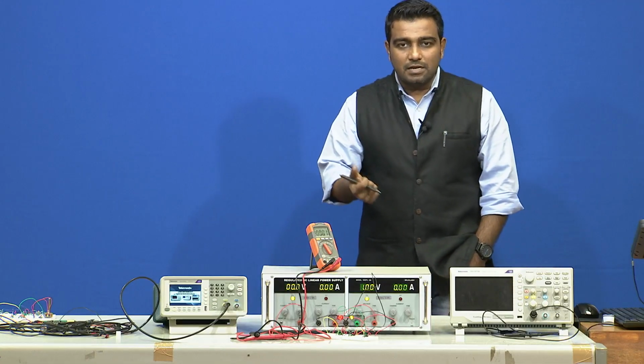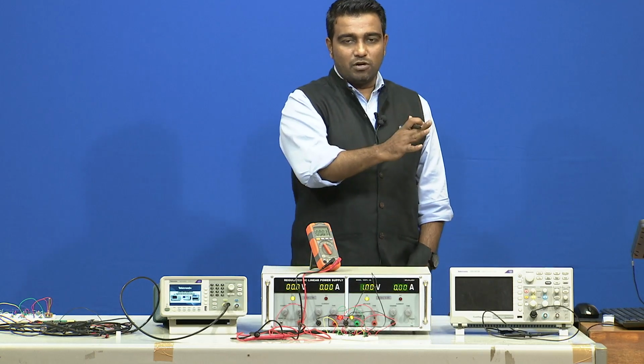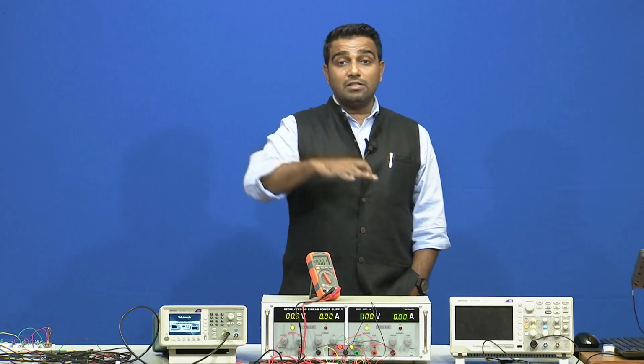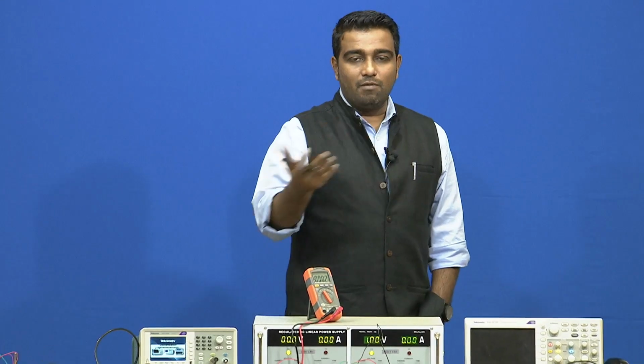Suppose I have a sensor which is a resistor sensor and I connect it to a potential divider, and if I connect the potential divider to the inverting amplifier, you will see a loading effect. To remove that loading effect, if I put a buffer in between, then I can remove the loading effect. That is the use of my buffer. So, you are not only explaining how you are using the buffer, but also where to use it, with a given example of a sensor, right. When you talk about this whole circuit, it gives a clear understanding, and we have in fact seen in the experiment how the loading effect can be removed, right.